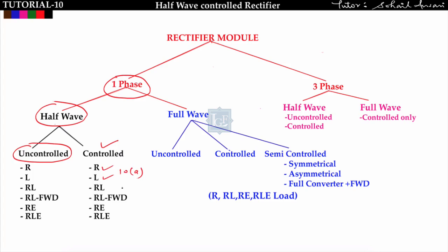Before moving into this lecture I would like to give you one important point. In all the previous 3 lectures, suppose you have to find the input power factor, we are putting input power P in equal to P out. P in is source RMS voltage, source RMS current cos phi, which is equal to P out, right? And for output power we have to see whether the load is voltage stiff type of load or current stiff type of load. Now to find the source RMS current, you have to see whether the source RMS current is equal to the load RMS current or not.